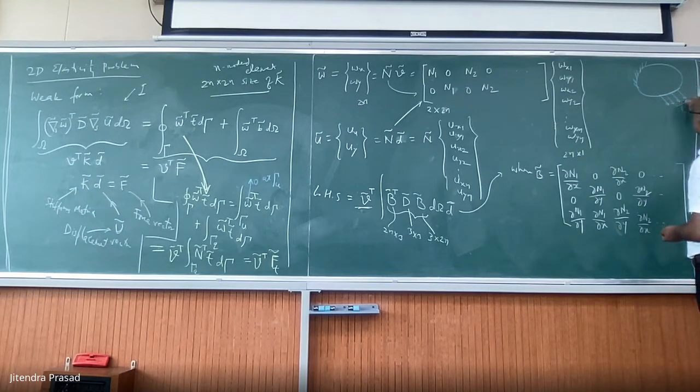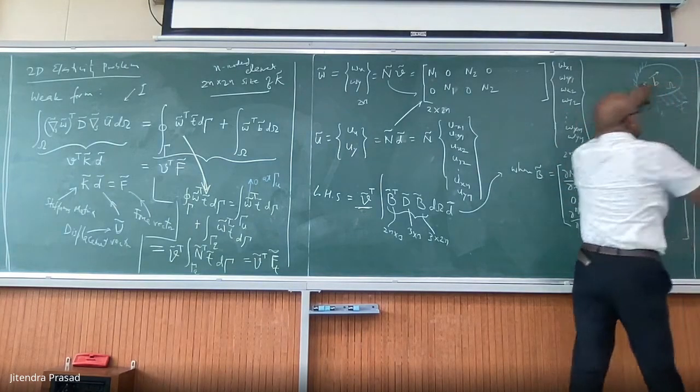So we give the forces on the surface. So from there, the force vector will be constructed. The other one is where you are giving the body force. The body force will be defined on omega. This traction will be defined on gamma T. So you have to construct the force because of both of them.